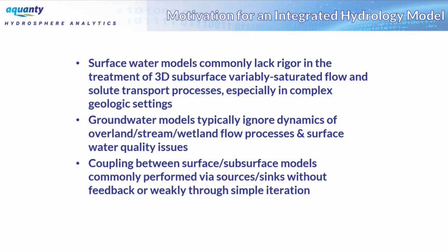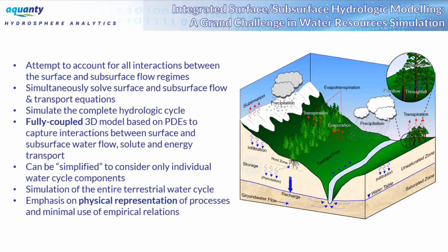So with a fully integrated model like HydroGeoSphere, we'll typically handle all of the processes that you see listed on the right-hand side of the screen. They're handled internally by HydroGeoSphere. They become part of the solution to your model rather than being a prescribed mathematical forcing function. The one exception, of course, is precipitation. The great thing about a fully integrated model is that the primary forcing function, which is precipitation, is directly observable and measurable. The data is widely available.